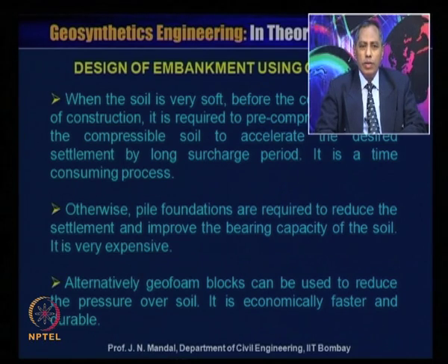Otherwise, normally we go for pile foundation which is required to reduce the settlement and improve the bearing capacity of the soil. It is very expensive. Alternatively, geofoam block can be used to reduce the pressure over the soil. It is economical, faster and durable.